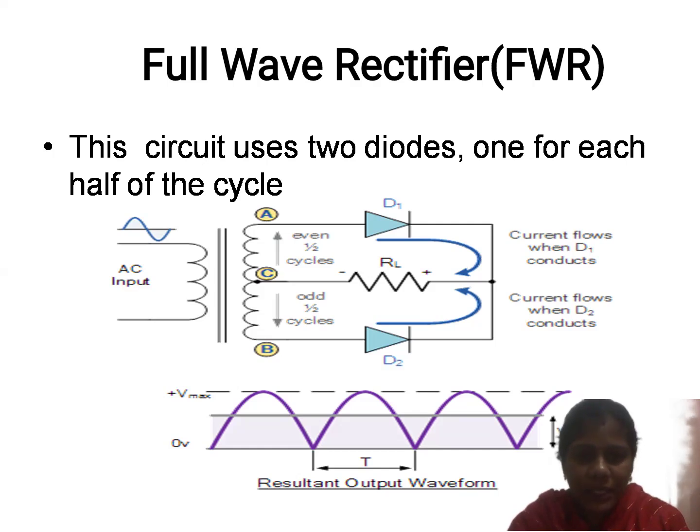Using these conditions, diode D1 will be under forward bias and diode D2 under reverse bias. This holds for the positive input cycle. Whenever diode D1 is forward biased, it is in short circuit, and similarly diode D2 can be replaced by an open circuit.